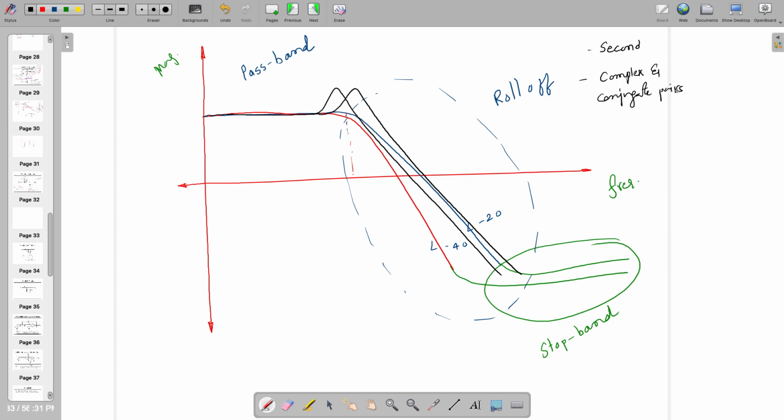Then this will happen. To avoid that, maybe you can avoid L and C, but without L and C the order of the system cannot be created, right? So if those values have been taken poorly, then you may have such kind of overshoot, which is not desirable, right? Those who are studying control, you must have seen over damping and under damping systems, right? That is happening only when you have inductor and capacitor.